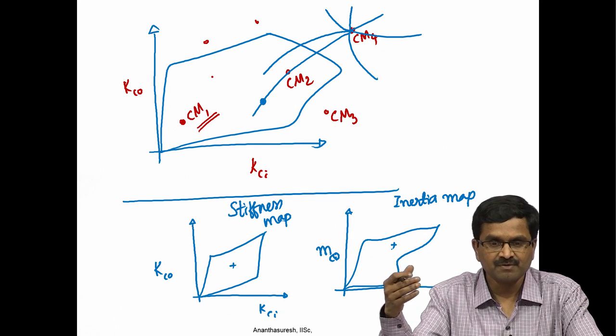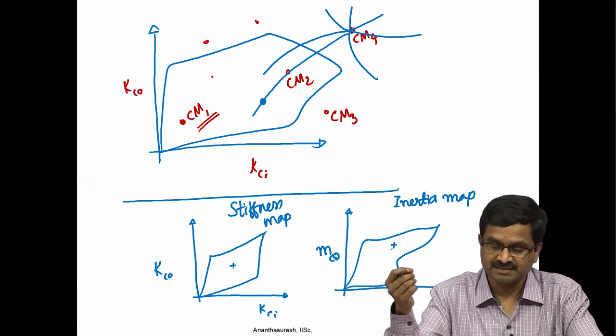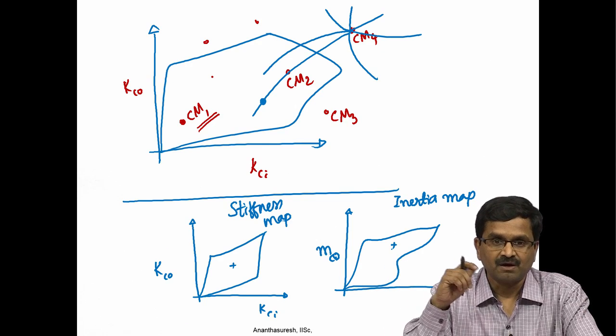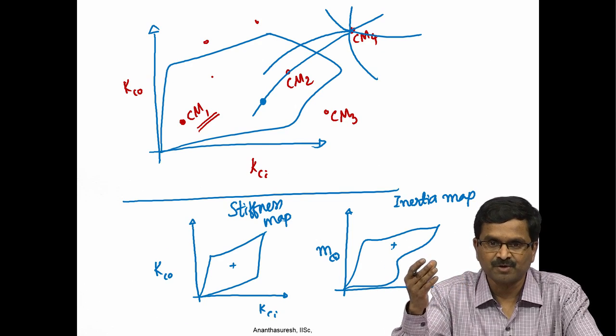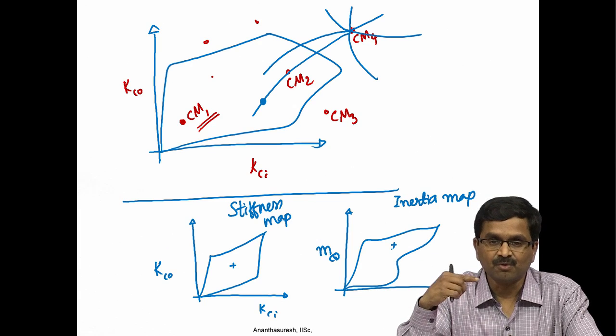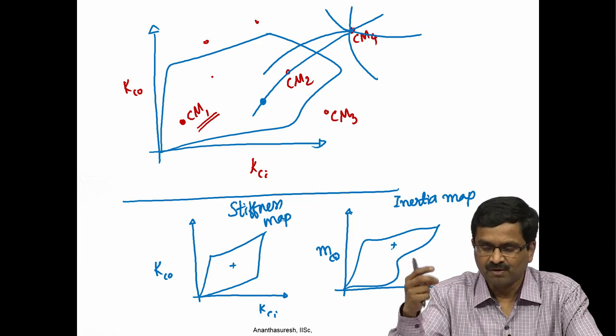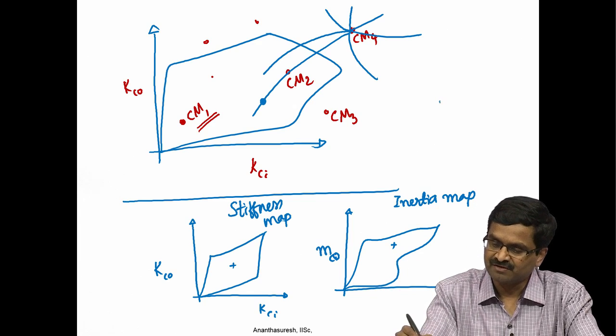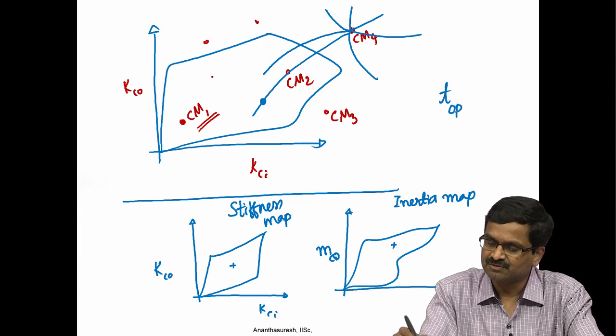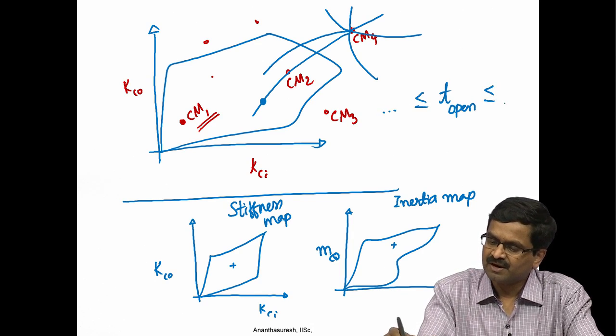we might also have dynamic considerations such as natural frequency or time for a certain task. Let us say it is the valve problem we discussed, where the valve should open within some time. All of those dynamic considerations can be kept, and the user can specify, for example, time to open, T open, with a lower bound and upper bound.